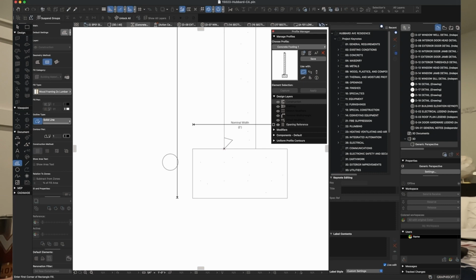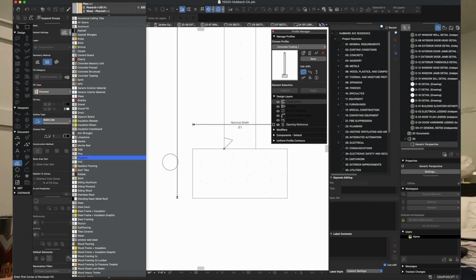Now the next thing I'm going to do is take this fill tool, and before I actually do the foundation gravel chimney, I'm going to create a protection board. Now the protection board can often be insulation. Sometimes if you don't have the insulation on the outside, it can be just a piece of lumber. A lot of times in this environment we just put insulation. Sometimes it's even just protection, like putting up a bituminous coating on the foundation.